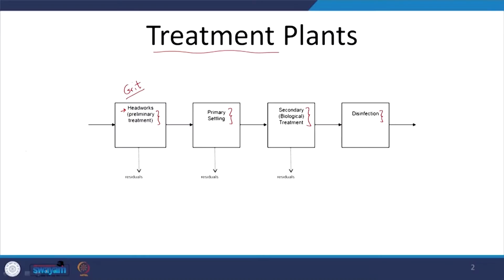So, here you are out here, and typically the wastewater treatment plant is constructed at a lower elevation. So, by gravity your sewage is going to flow from your particular home to the STP, the sewage treatment plant. For the wastewater to go from headworks to primary settling, then to secondary treatment, and then to disinfection, you need flow from one unit process to the other.